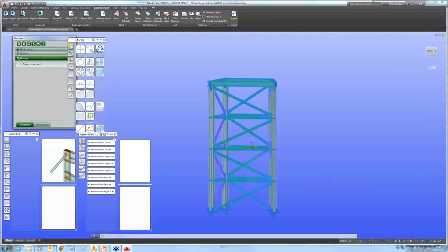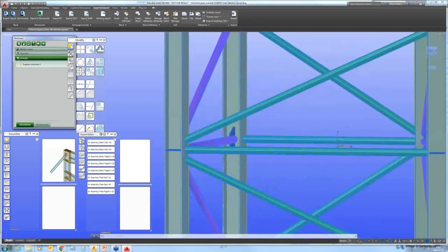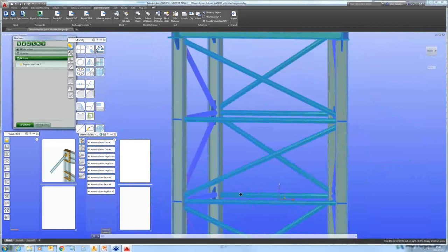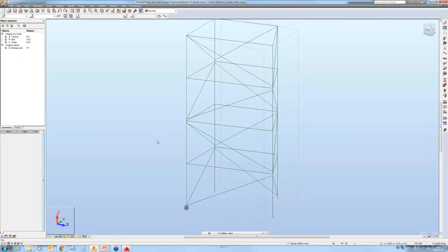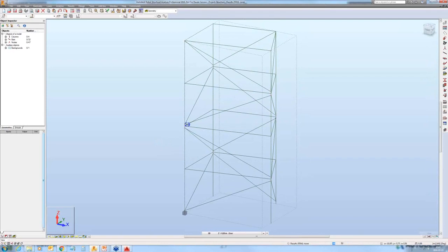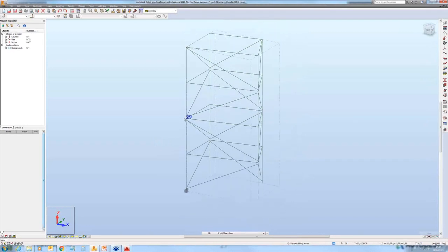So what I'm going to do, I'm going to show you for a moment in advanced steel the fact that this model has got a certain connections defined. And these connections include the gaps. So there is no common point for these elements. They are with gaps. But in robot, to, for example, use the steel connection module or to have coherent results, we want to have all these elements to be actually snapped to a single position.